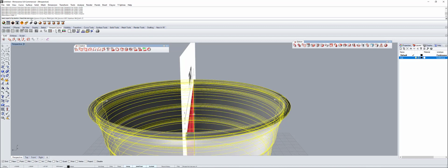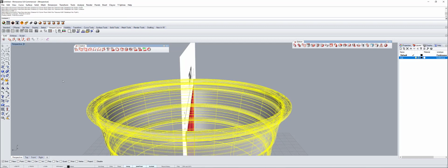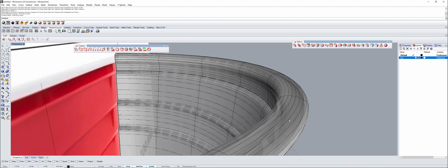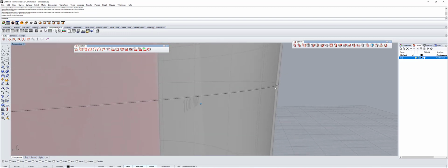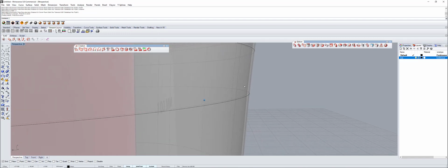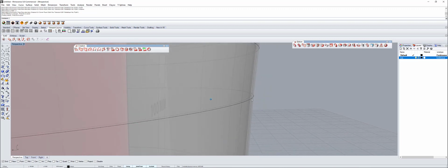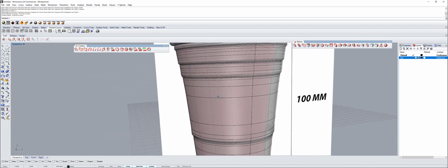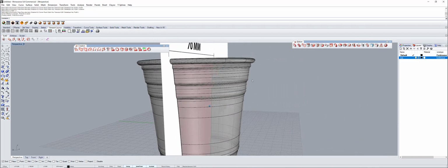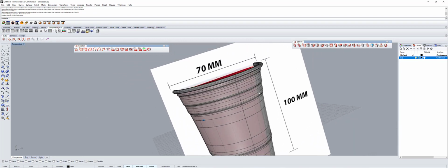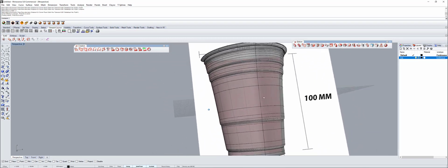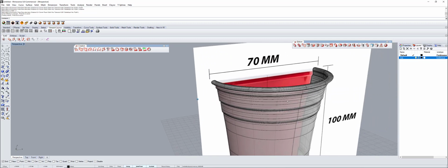So now our surface is gonna be a solid. So enter again, and you see how it's gonna go. You see how it changed the shape. Now it's bigger. And now remember that I was telling you that we didn't see this when it was ghost. Now you see we got two surfaces, but it's really a solid, not a surface. Remember, it's not a surface anymore. So yeah guys, that's the cup. Now we got a cup. Now you can print it.